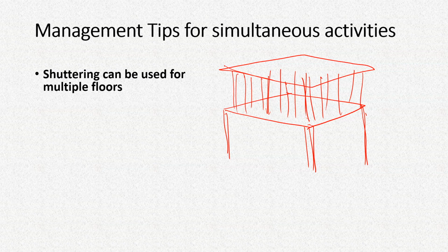So it's better to cast all the slabs as quickly as possible, so that the same shuttering material can be used for all of them.